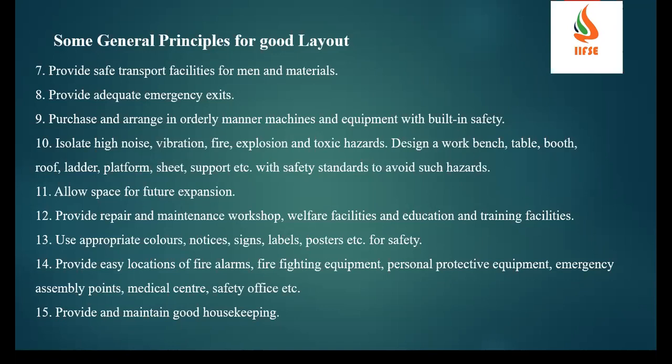And provide easy location for fire alarm, firefighting equipment, personal protective equipments, emergency assembly points, medical center, and also safety office. So easy locations, and simply I can say that wherever we have an emergency exit, there we used to put all these fire alarms like MCPs, manual call points, and we used to put emergency masks.